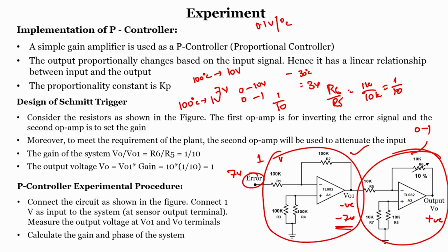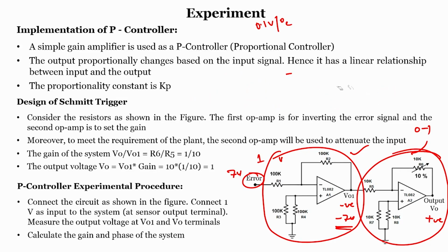That is the output from the controller, right. So, what exactly are we doing? If I want to realize it in a graphical way, this is the graphical representation. For 0 it is at 0, for 100 degree centigrade it is 10 volt. Now, I am changing the scale from 0 to 1 volt. Why?